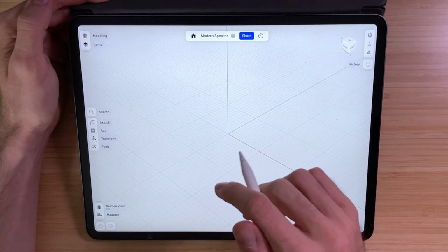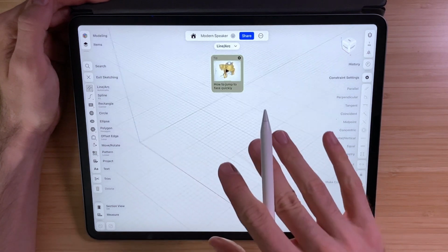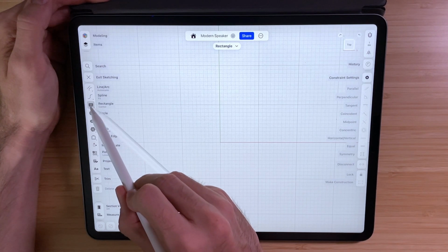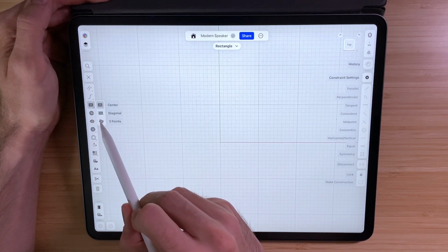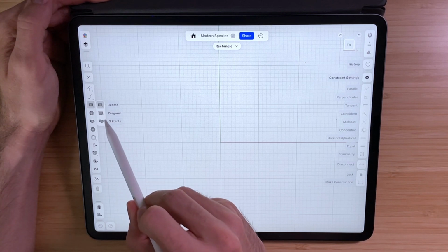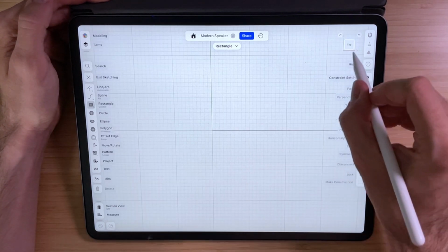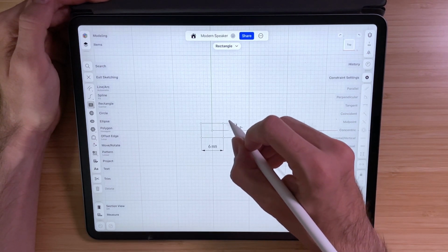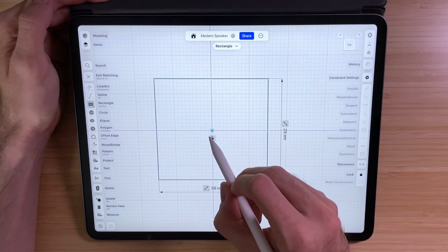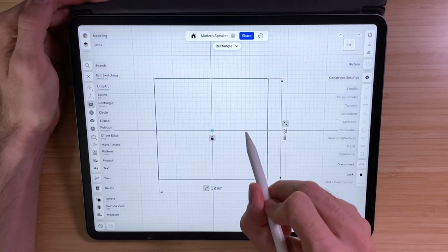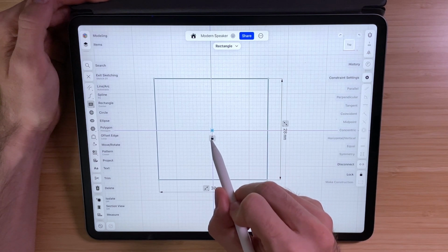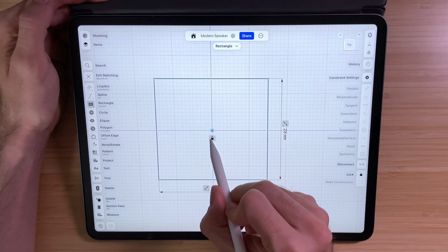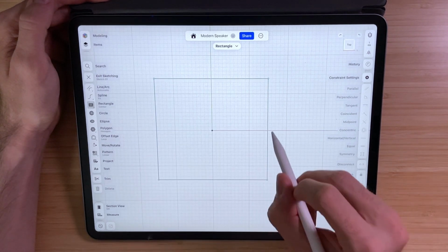For our first step, let's go ahead and create our sketch from the top view, and we'll create a center rectangle. If you don't see center here, just double click or highlight and go down into this drop-down menu, and then select the center rectangle from the menu. Since we have snapping on, let's hover over the center point roughly, and then create our rectangle. That makes sure that the center of the rectangle is also the center of the axis. And to make sure that it doesn't move whenever we add any dimensions to it, let's also click lock in order to lock the rectangle in place.